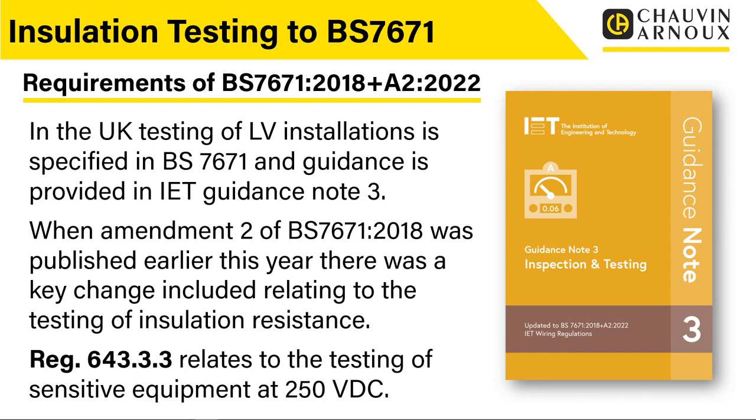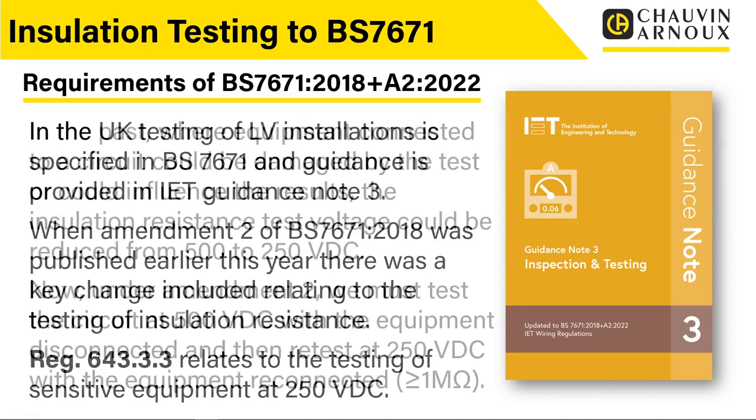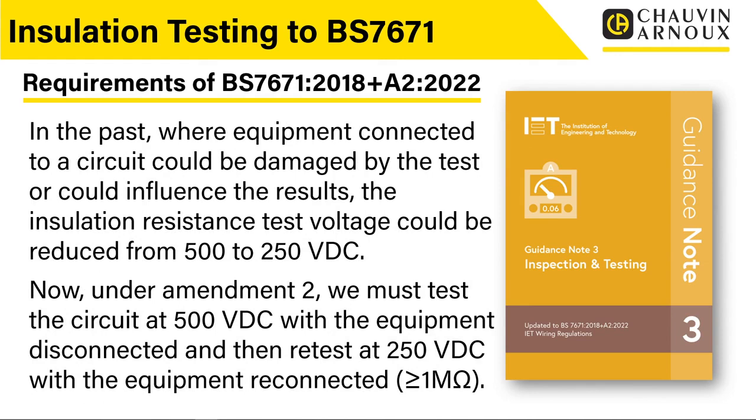Regulation 643.3.3 relates to the testing of sensitive equipment at 250 volts DC. That's the specific bit that's changed. This is the nuance that's come into the testing. So let's have a look at that in a bit more detail.